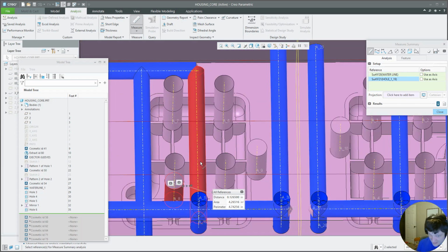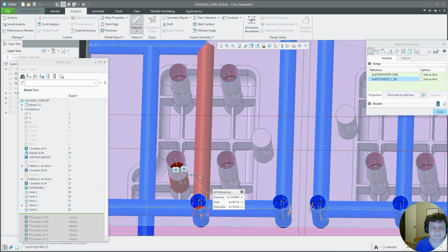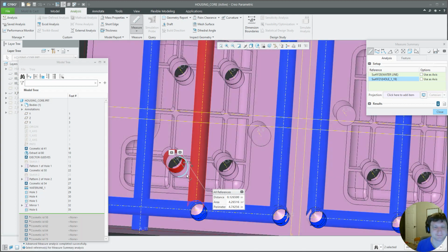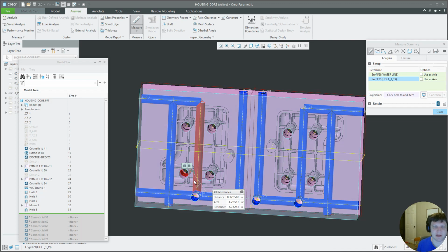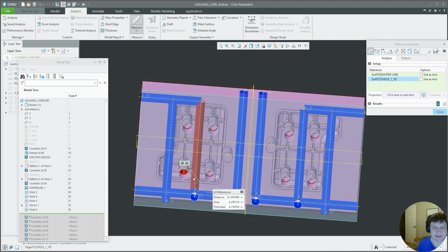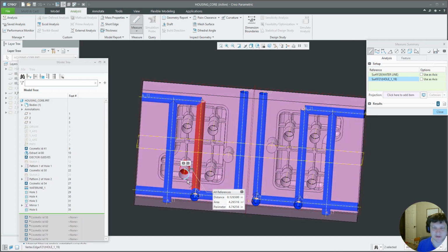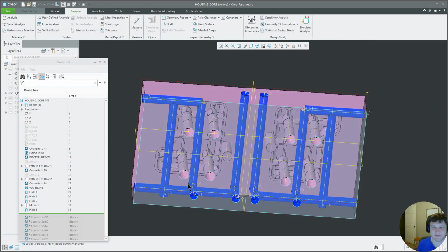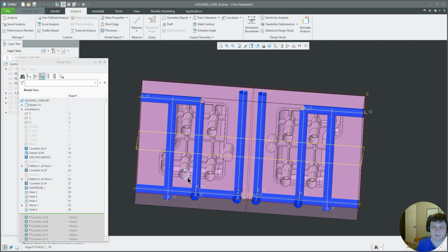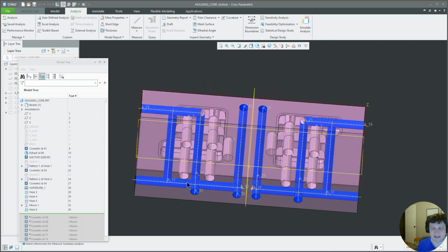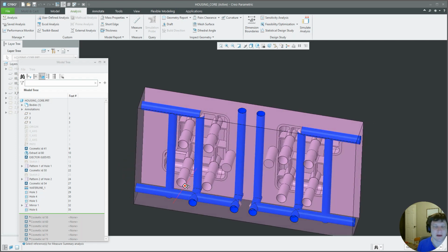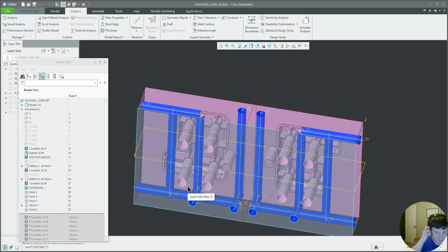Depends on who the mold maker is, if they're going to be comfortable with that. Personally, I'd probably drill it that way. This small of a block, you're not going to have that much walk in your drill bits, as long as you take it slow. So, at least for now, we'll leave it until we talk with a mold builder, discuss it, and make sure it's okay with their process. Like I said, it depends on the mold builder. I've had it either way.